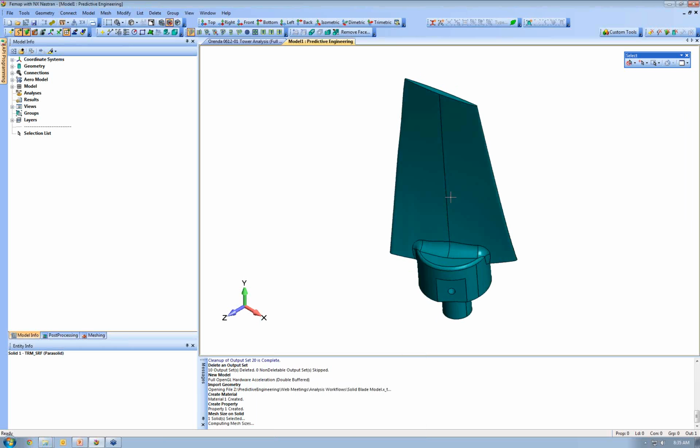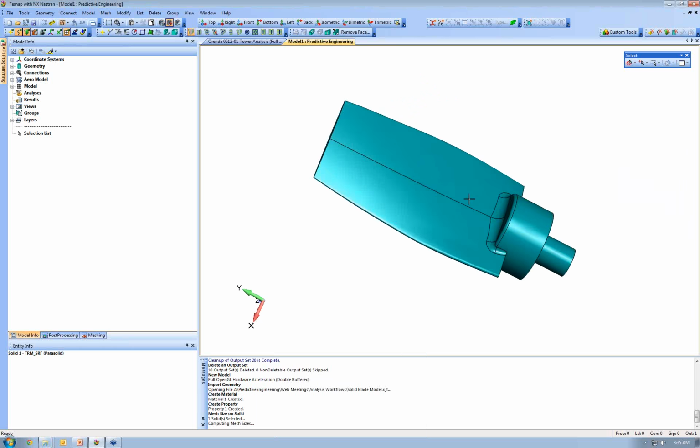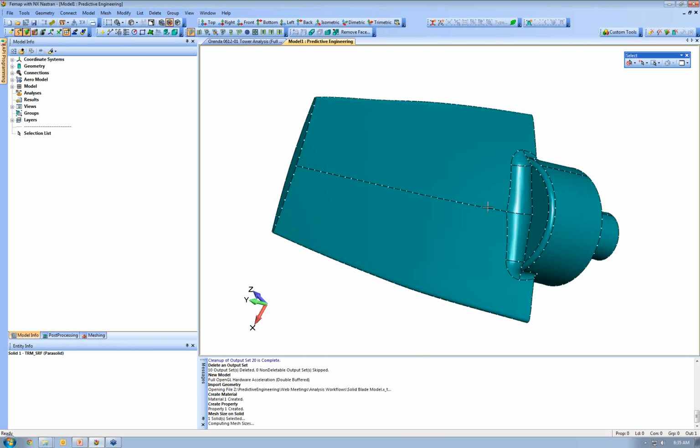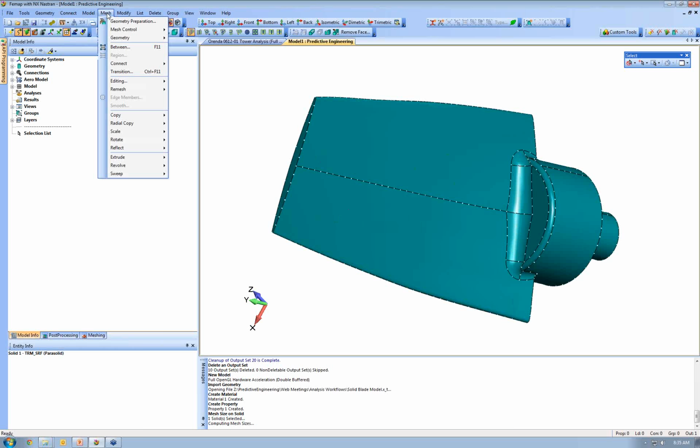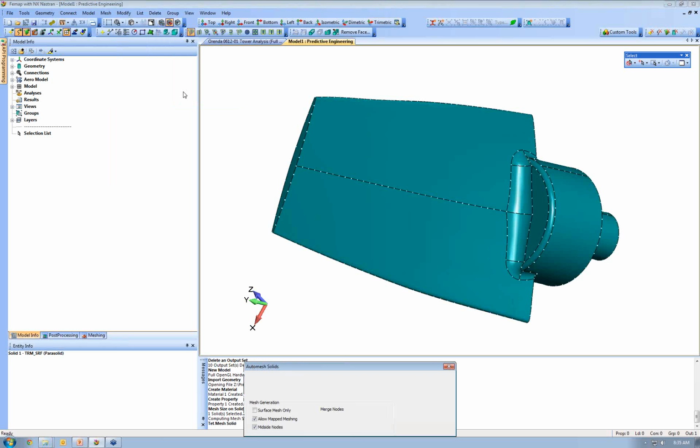And you can see what happens here is that it puts a little mesh sizing along the curves. So you've got an initial idea of, all right, how coarse, how fine is this mesh going to be? All right, next I'm ready to mesh, Geometry, Solids. Now notice that there's hex mesh solids and just solids. And the one that says just solids is a tetrahedral mesh, and you can see by the little icon there.